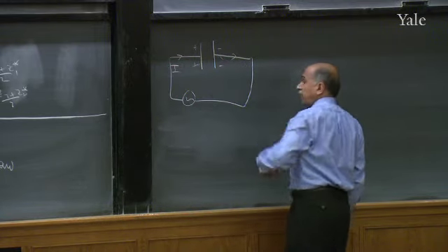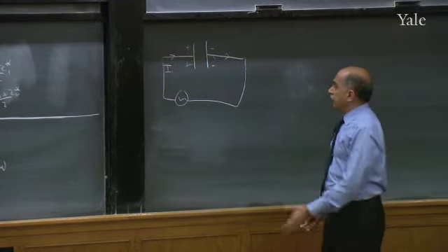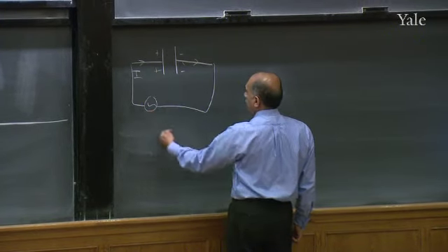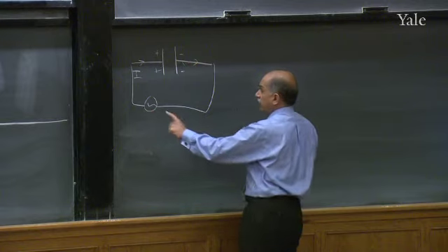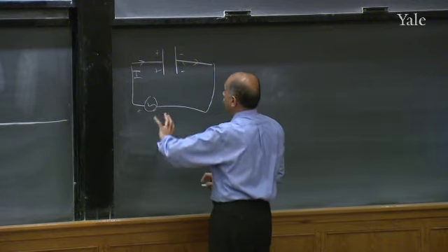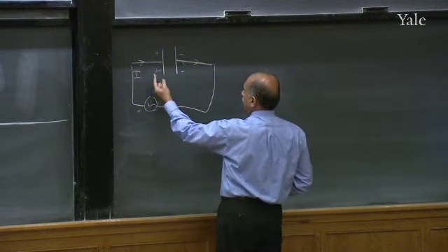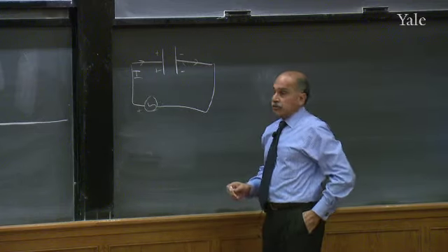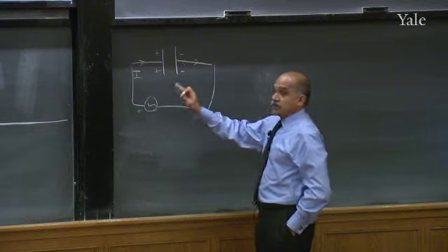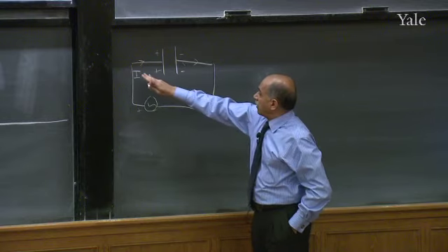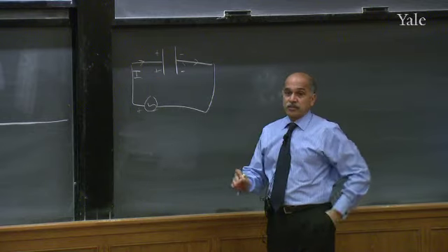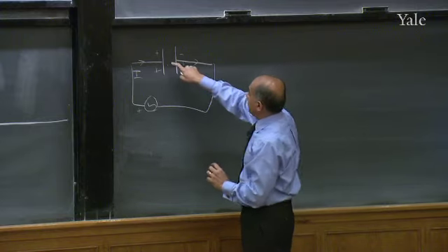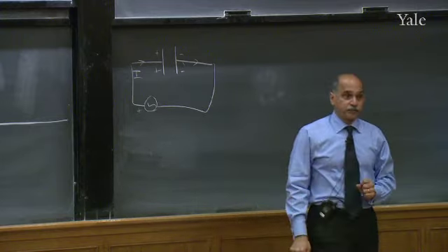I want you all to know what's going on. Nothing really flows through the gap in the capacitor. It's not possible. What happens is, for a while, plus charges rush here and minus charges rush to the other plate because that's the polarity of my AC source. Later on, it's reversed. Then minus charges go here and plus charges go there. So there is an alternating current in the circuit, but there is no current flowing right through in one sense. But there's nothing to keep it from going this way and that way, because they don't have to jump the gap to do that.